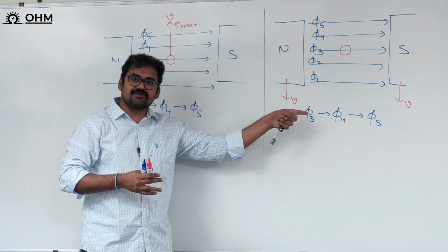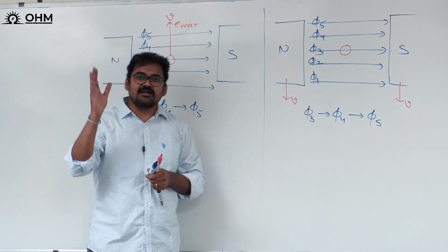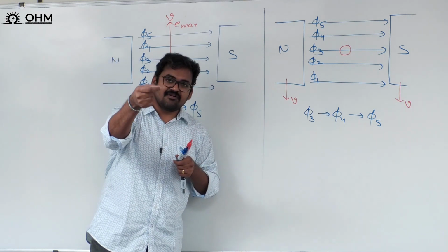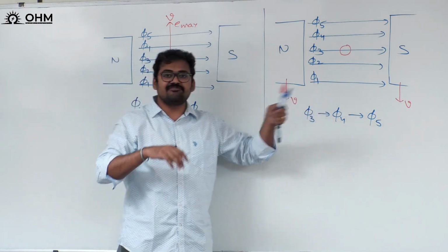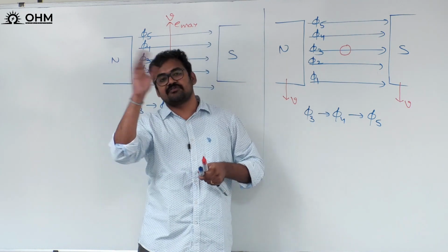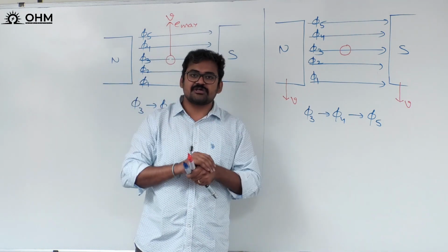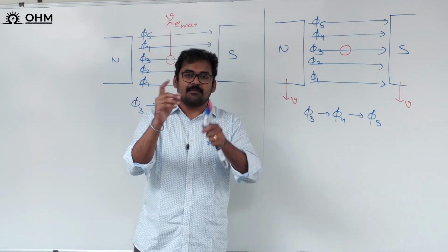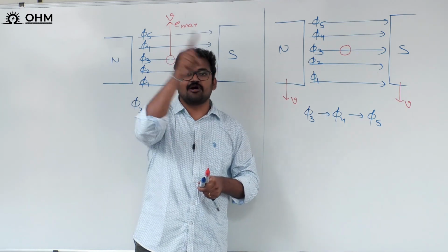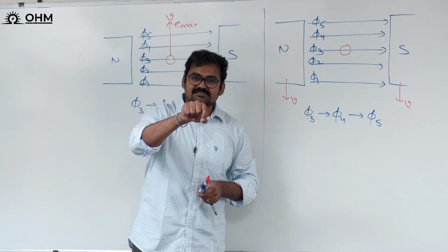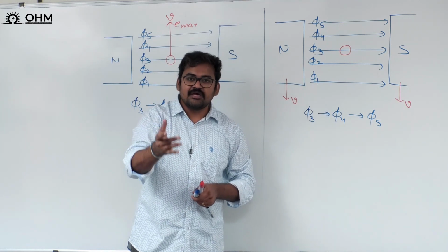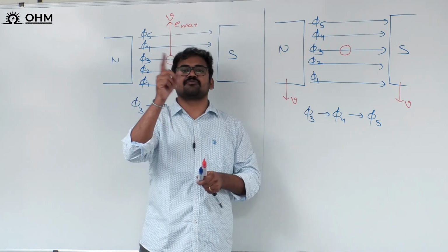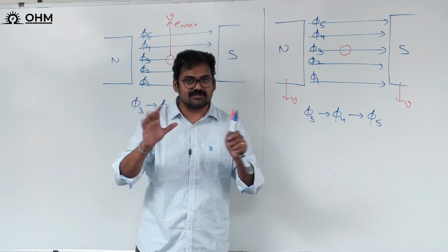So from this concept, a conductor moving in clockwise direction is equivalent to a magnetic field moving in anti-clockwise direction. Suppose I gave you a question: conductor is stationary, magnetic field is rotating in clockwise direction. That case is very similar to magnetic field stationary but conductor moving in anti-clockwise direction. Both are similar.